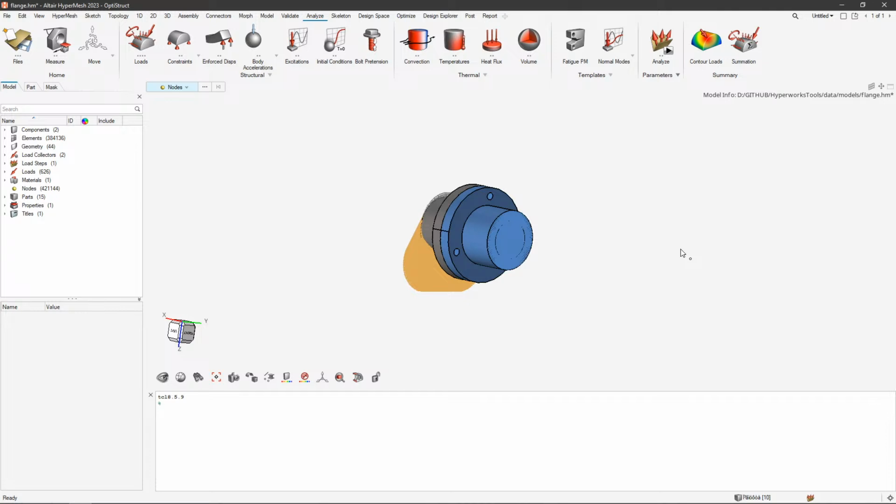Well, subgraph, we're not using the subgraph anymore. We are using just one time the graph of the full model, and we're using then the connected groups we get from the complete graph. We're using that for each and every RBE element. But the intersection calculation should be pretty easy. If that's not optimized, there are certain tricks of how to optimize it.